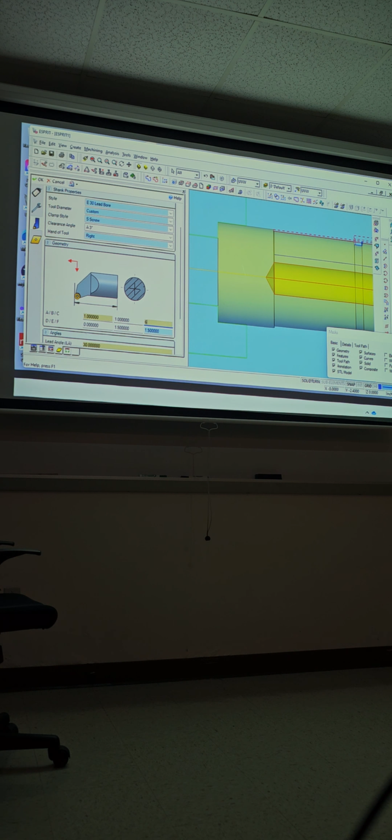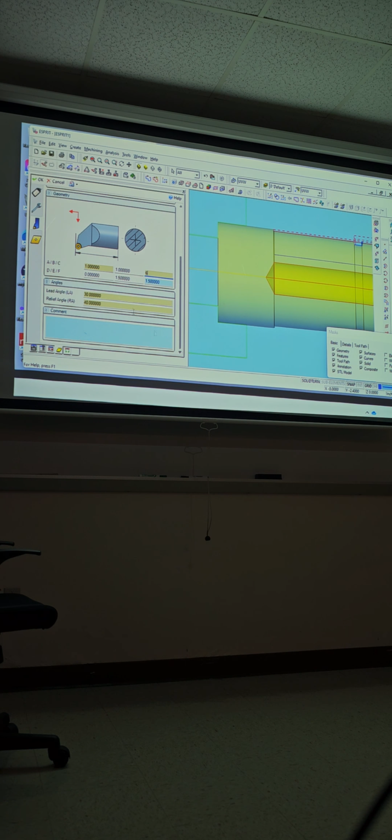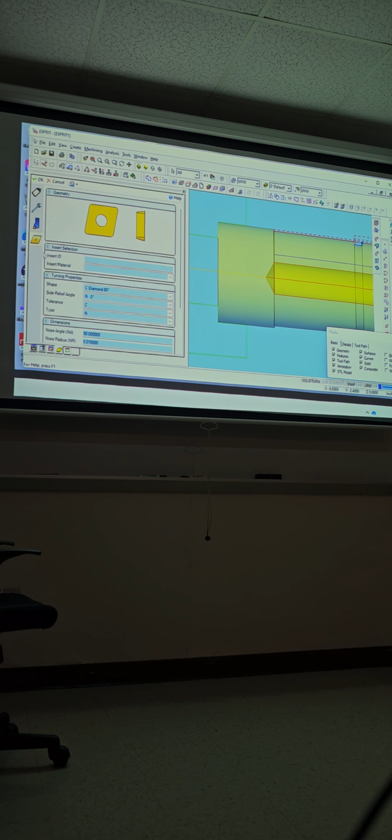What are they telling you? What is a good rule of thumb that you have to give him extra space? What do they say? 1 inch? Relief. Usually it's no more than 1 inch. Why? Because it's gonna vibrate. Chatter. That's gonna chatter. That's correct. All right, so 6 inches. That's good. We go to the next tab. We're almost there, guys. Promise.